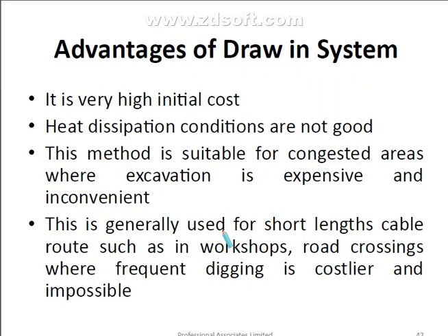The drawn-in system has a number of advantages. The initial cost is high, but as compared to its capability to rectify faults, the overall maintenance cost is comparable. Heat dissipation is a major concern, and it is not so good in this system, so that is a disadvantage of the drawn-in system. But this method is suitable where direct laying was lacking.